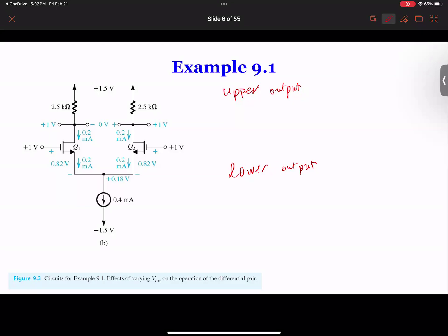So we use VD minus VS is VDS, right? So let's do that. VD minus VS, so that's VDS, and it has to be larger than VOV, and VOV equal to VG minus VS, which is VGS, minus VT. So that's one step. So VOV is VGS minus VT. VGS is VG minus VS, right? So we got this equation here.